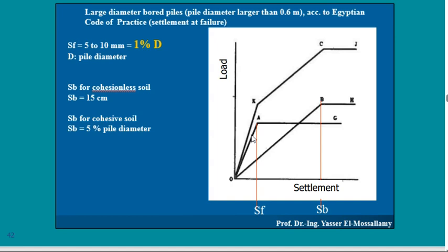If I take the minimum, then this is the minimum geotechnical load that can be carried by this pile, or really it will be carried by the soil, not the pile, because all our parameters are related to soil, not to pile. So it is the load that can be carried by the soil all around the pile to have a safe pile.